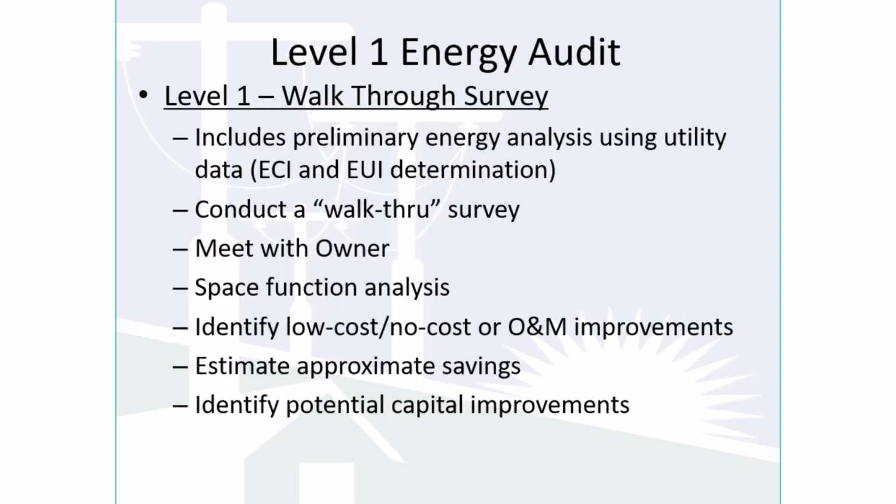So let's talk about a Level 1 energy audit. Very common. Sometimes people call this the walkthrough survey. The first thing you're going to do, of course, even before you go out to the site, is collect your utility data and try to determine the energy cost index and the energy utilization index.